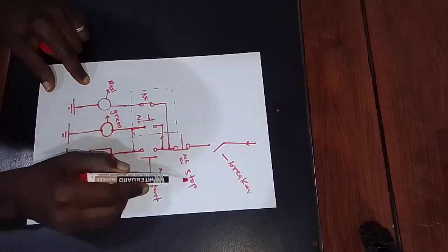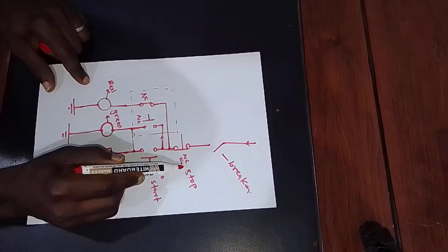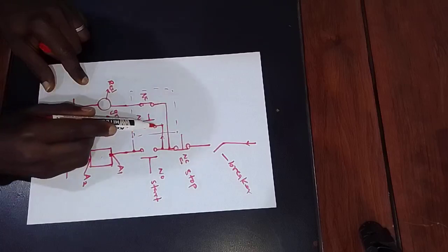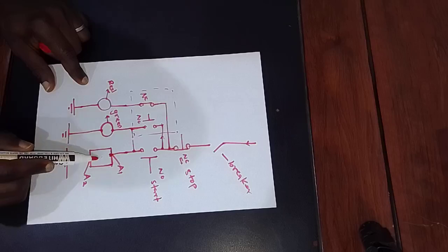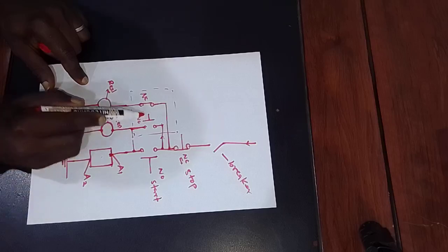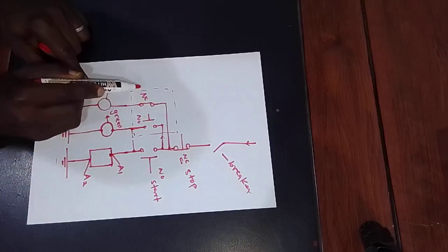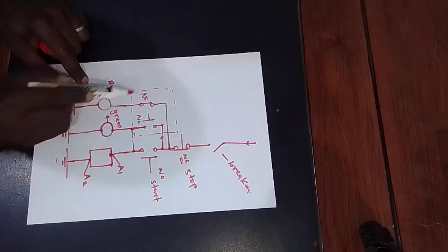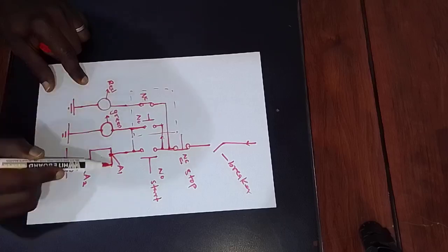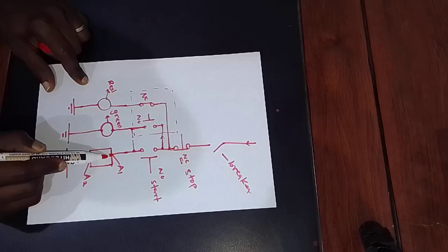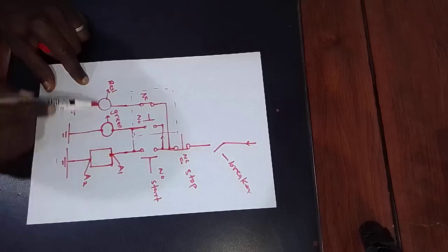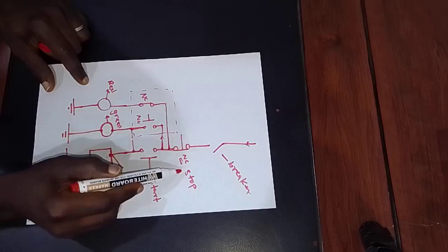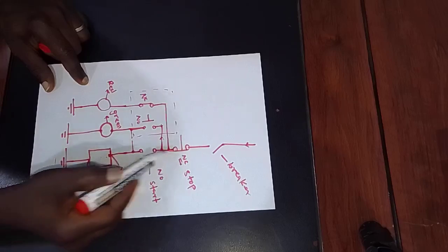But as soon as the stop push button is pressed to open the circuit, the contact that was closed when the coil was energized opens, and the contact that was open when the coil was energized closes as soon as the coil is de-energized, giving you the red light, showing you that this particular circuit is open or switched off. That is, the load is switched off.